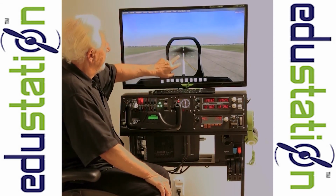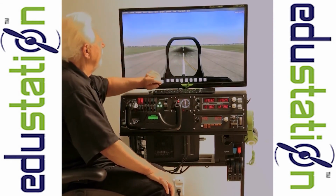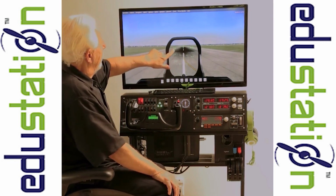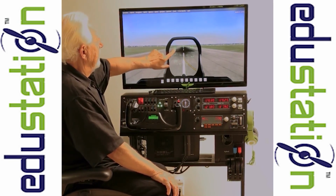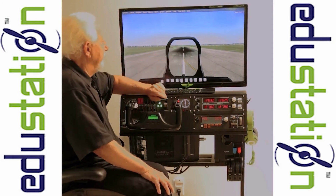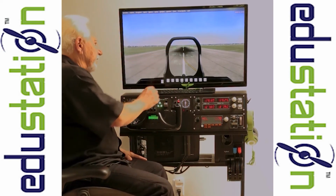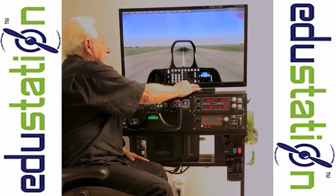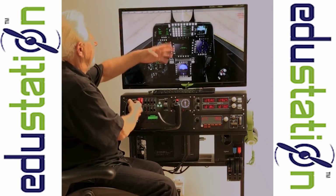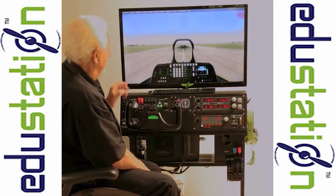You'll notice that you'll see a mark for 5 degrees low, 10 degrees low, and conversely, as you go up, you'll see markers for pitch up. We're at 48 knots, that's as slow as this airplane's knot meter goes. We're 170 feet above mean sea level, and we're on a heading of 356 degrees. We can at any time look around the cockpit and activate any of the instruments. This is our artificial horizon.